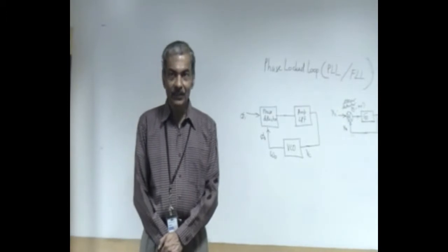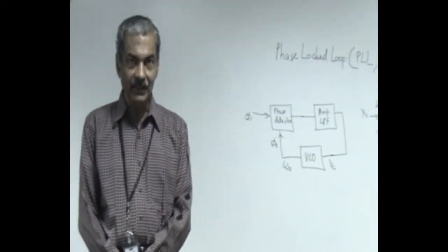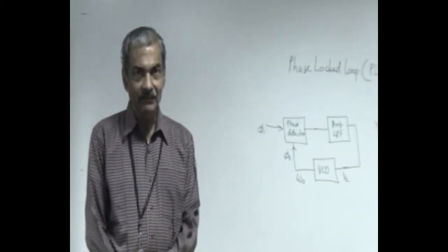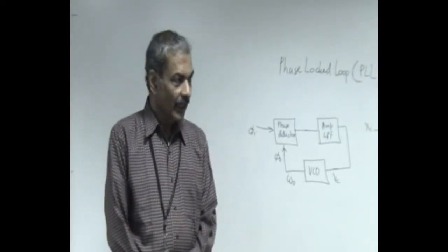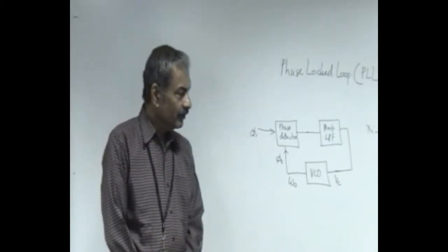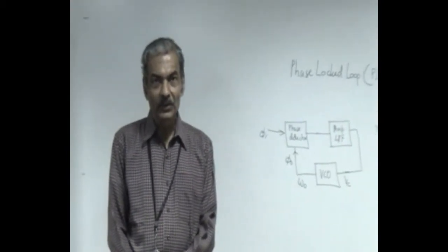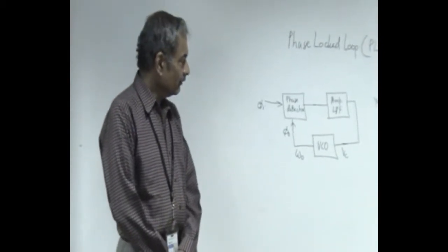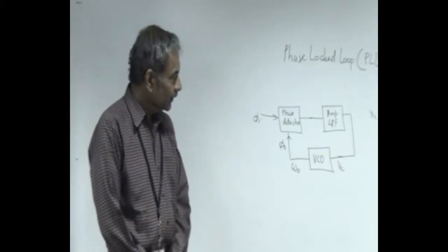We'll see that the phase lock loop is, in a strict sense, valid for the self-tune filter, where we were able to lock the phase of the system to pi/2, and that happens when the incoming frequency and the frequency of the filter pole are the same. So today I'll elaborate more about feedback systems.